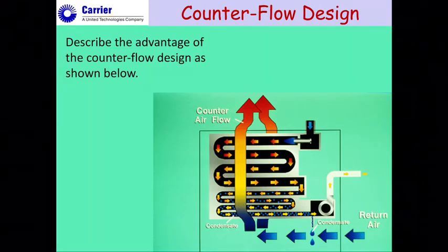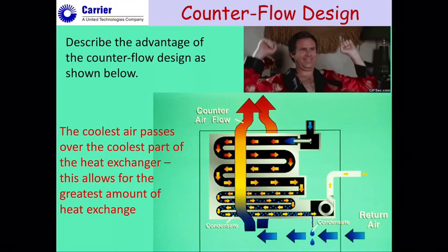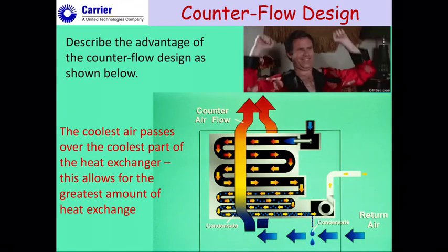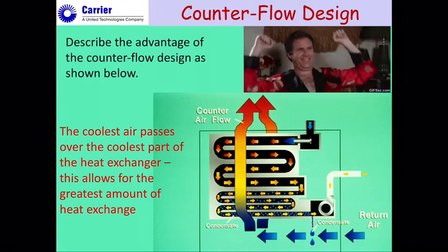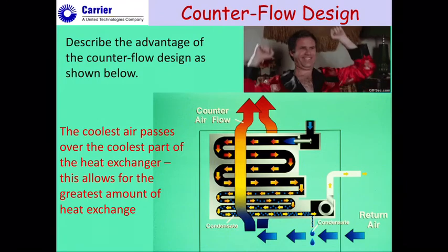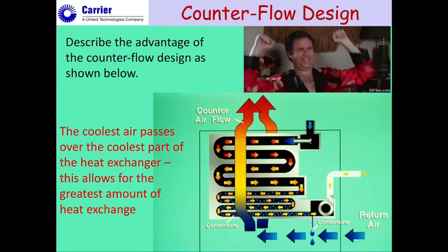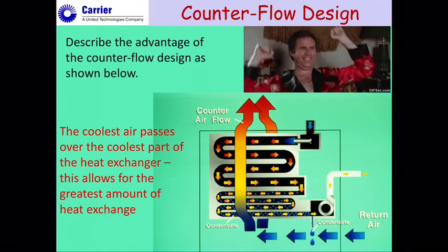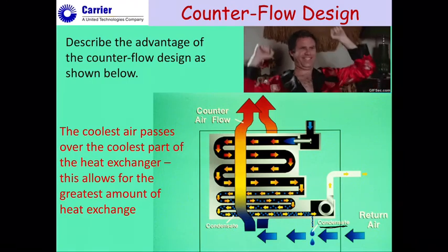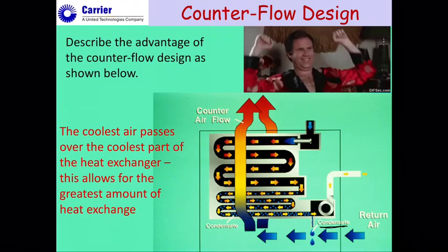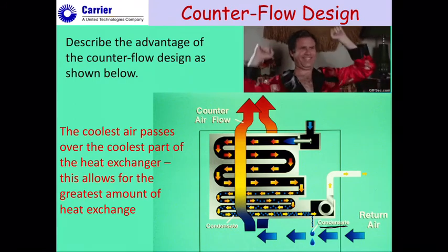So what is the advantage of that design? What I'm going to talk about specifically is what they call a counterflow design. The intent of the counterflow design is such that we can achieve very high efficiency on heat transfer. If we take an appliance and we can somehow cause the coldest return air to hit the coldest temperatures of the flue gases in a high efficiency heat exchanger, we can cause those gases to drop lower and lower and lower, and even provide us better condensate extraction, we'll call it, from the flue gases.